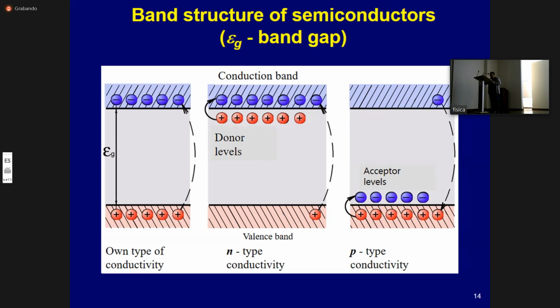In the absence of external voltage, the extent of the depleted layer is very small, on the order of a micrometer. However, the width of the depletion region increases when so-called reverse bias is applied to the p-n junction. The external voltage is connected in such a way that minus is applied to the p region and plus to the n region.